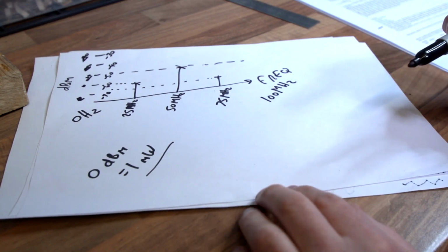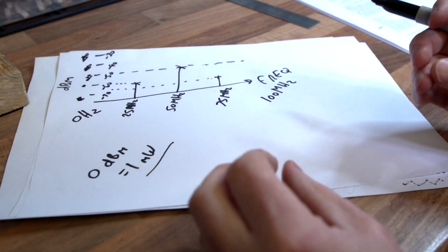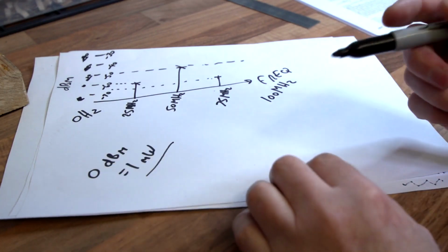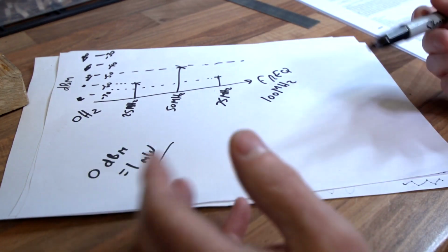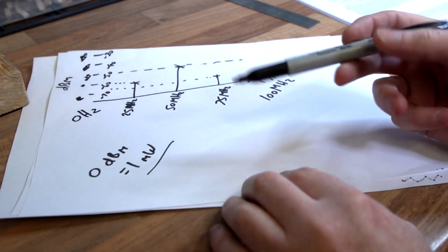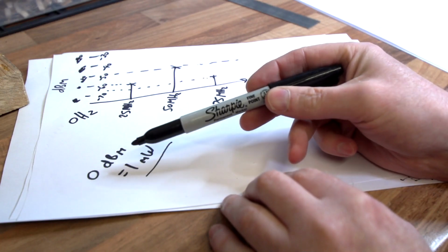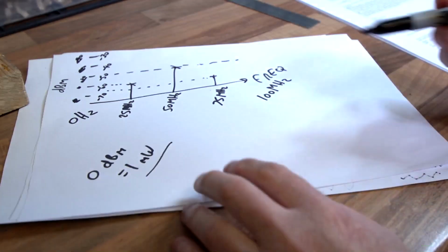And with spectrum analyzers, we usually are working with measuring very small signals, like in the receiver side of a signal. It could be just picowatts or something. And on a transmitter of a radio, we could be talking about megawatts or even higher. So that's why we use the logarithmic scale. That's why we use dBs, because dBs by their very nature are logarithmic, they're not linear, and it allows you to fit everything into the same scale. Really, really useful, and that's why they do it.